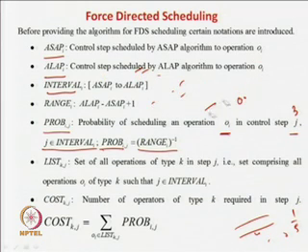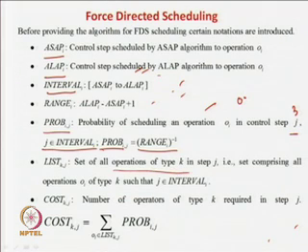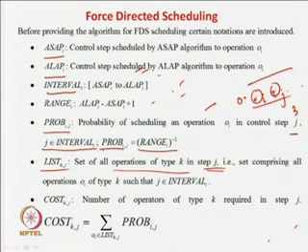Then finally we have another thing called the list Kj. What is the list Kj? It is the set of all operations of type K in step j. So in a step you can schedule, say, a multiplier operation, that is Oi is a multiplier operation, then Oj is an addition operation and so forth. So in time step j, the set of all operation types K, which can be multiplier, adder, subtractor, divider, whatever is possible in that time step, we call the list Kj.